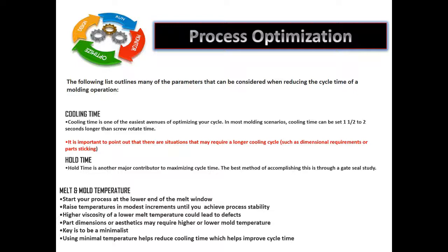But the primary thing to remember is that the key here is to be a minimalist. You want to start at the low end so that you can try to keep your cycle time low, and then add back in to get a premium part. And using minimal temperature helps reduce cooling time, which also helps improve cycle time.